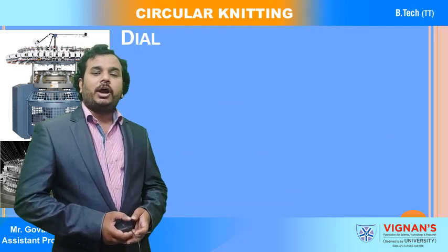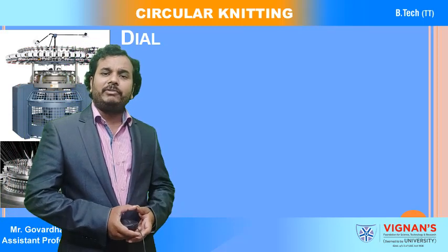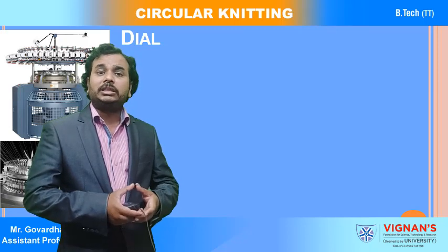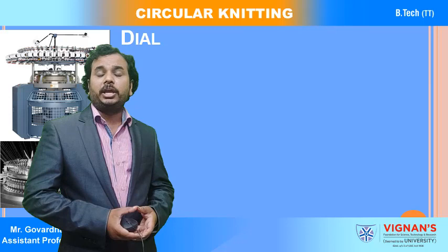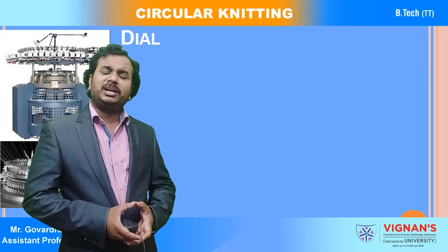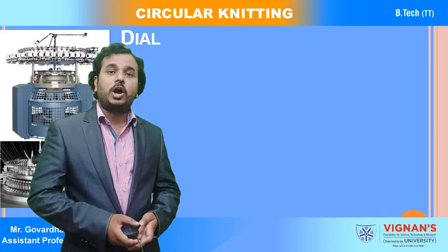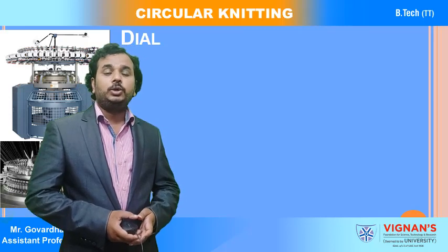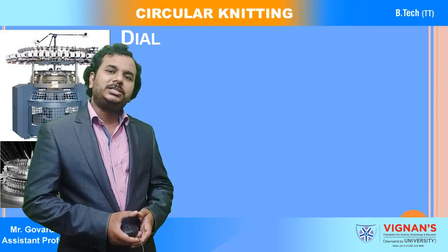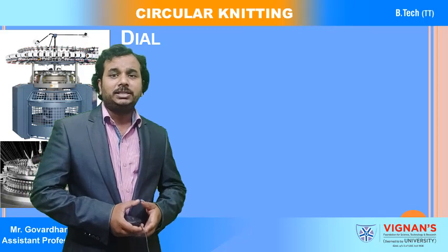Okay, and I told the gauge of the knitting machine, so we can have a gauge of like 30 to 35. So 30 to 35 is the maximum gauge, and nowadays we have increased the gauge also. So 30 is nothing but 30 needles per 1 inch. Nothing but 30 slots are present in the cylinder. So in each and every slot, one needle is going to be accommodated. So in 1 inch all 30 grooves are there, and 30 needles will be accommodated in the cylinder.